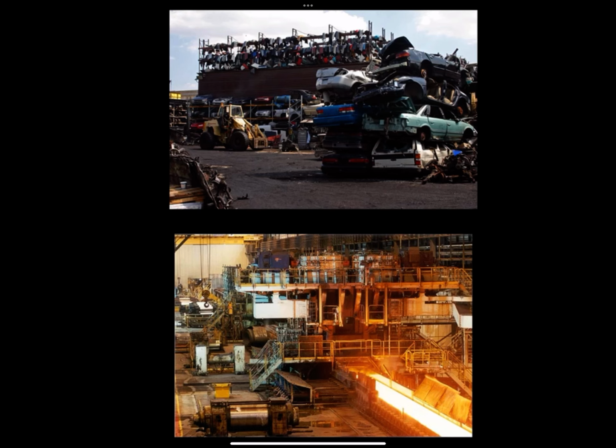The production process for mild steel or structural steel used in buildings is called hot rolling. And this is the image you see on the bottom. The element in the bottom right of the picture is a heated ingot of steel that's heated to white hot, which is then run through a series of rollers to produce structurally efficient shapes. So that's why with hot rolled steel sections, you often see radiused corners, because it's been produced through rolling.